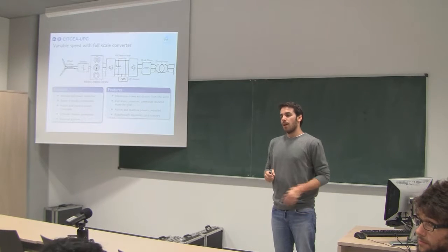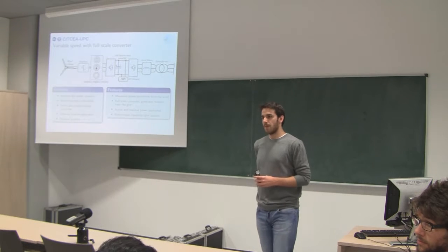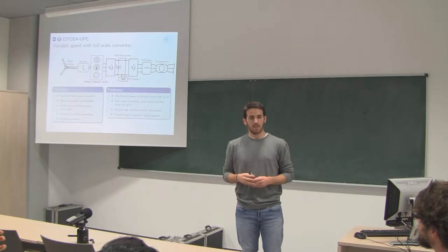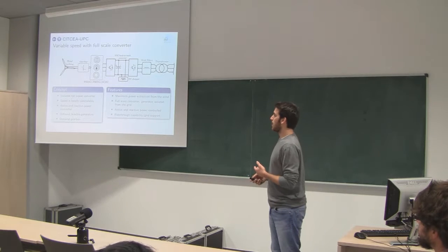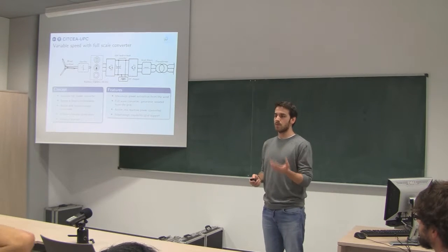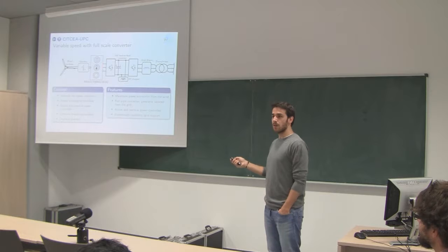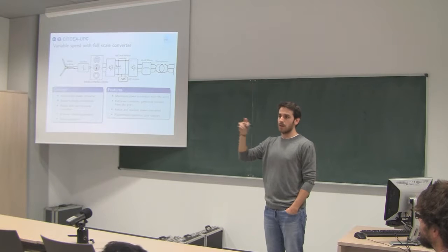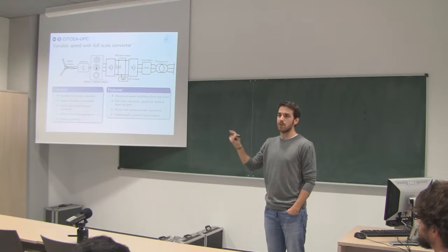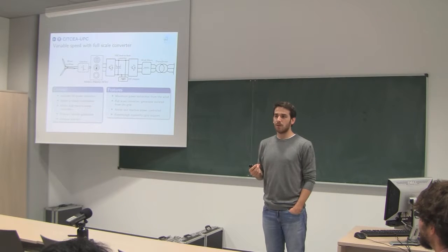Are there also approaches to connect the DC output directly to an HVDC link for offshore? Yeah, I think that Kevin will give some ideas about that, but there is also what is called a DC collection grid, which is being proposed for offshore wind. As soon as you have an AC to DC converter here, there are proposals for installing DC-DC converters to step up the voltage and then transmitting the power using HVDC transmission. Why hasn't this been realized yet? Well, I think it is a matter of cost.